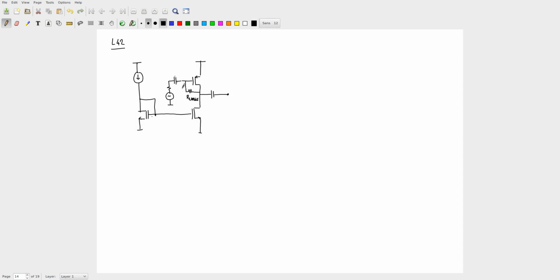One can have another version of the same circuit just for fun. Okay. I want to, instead of using drain feedback biasing, use a current source biasing for this transistor M1. Correct? So, what can I do? I'll have this transistor as it is. Similarly, that transistor as it is. And I'll just draw it slightly longer so that I can fit in what I want.